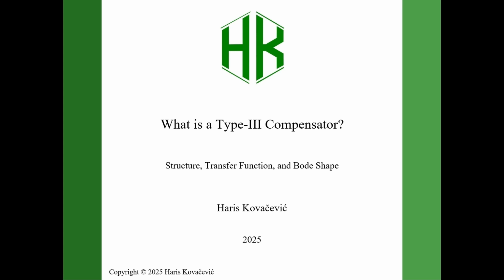In this video, I want to step back and answer a very fundamental question. What is a Type 3 compensator and why is it so widely used in power converter control loops? You will often see Type 3 compensators mentioned in buck, boost, and isolated converters, but many engineers use them without a clear intuition for what they actually do.